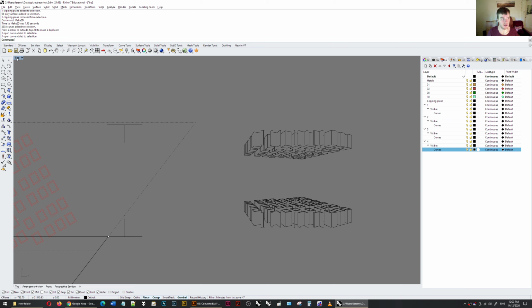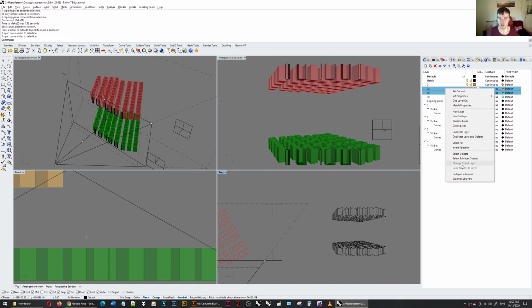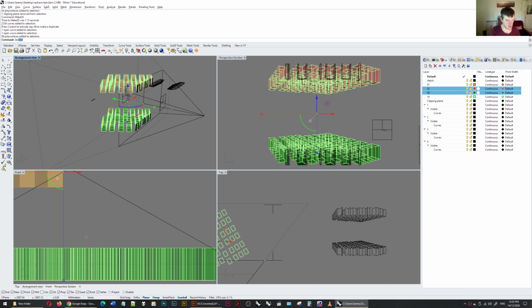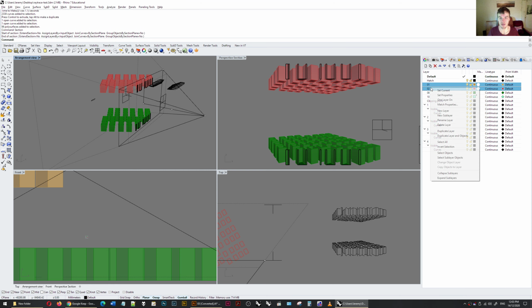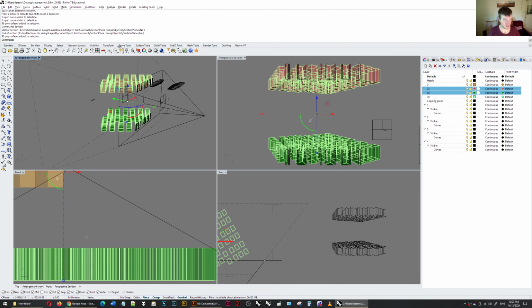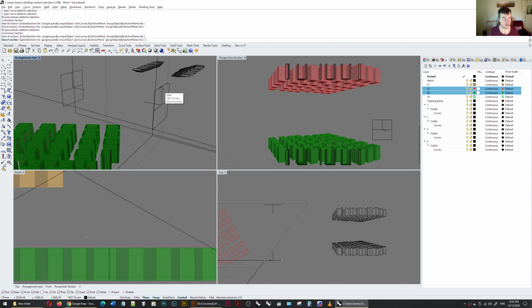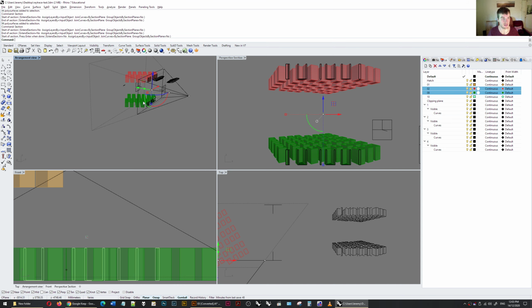And the final thing that we need is the section again. So the section will give us that pure cut. So I'm going to select these two, right click Objects, and I'm going to do the section commands. I start at this point. Select 1, 2, right click, select Objects, and section again, right click Section, start at the start of the clipping plane, tab to constrain the plane all the way across and press enter.